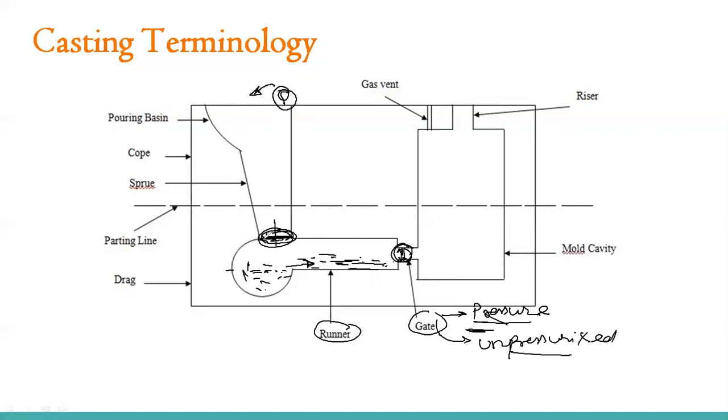If the flow is the same, and here the area is high, then whatever molten material is coming inside has space as well in this runner, the sprue or the pouring basin. So this molten material is basically filled inside this runner, it will enter inside this gate, and it will come out into the mold cavity through this gate.